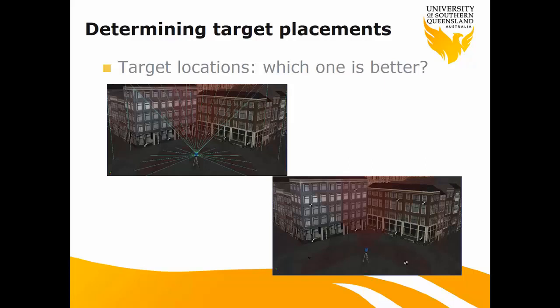When you study the photogrammetry and remote sensing course, you know that for orthorectification, we need GCPs, or ground control points, evenly distributed, and then you can get a very good result for the orthorectification. The same thing applies here. Otherwise, if you use the first situation, that will affect your registration, or sometimes you even fail your automatic registration.